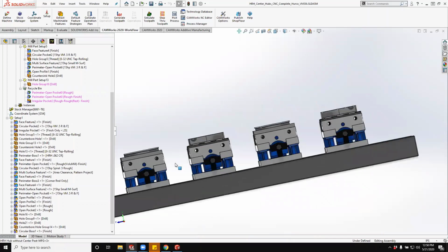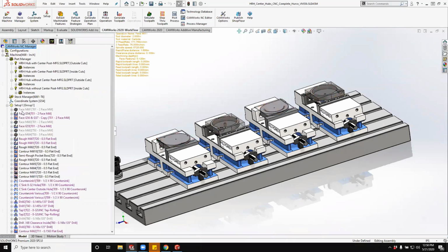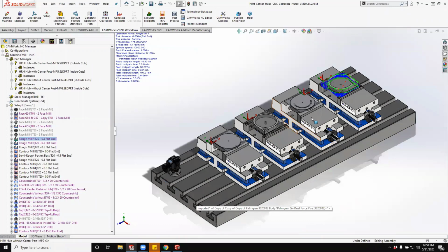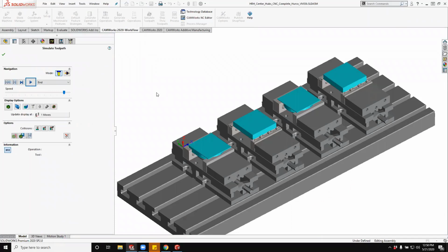And so when you go up to the CAM Professional, it gives you the ability to machine in the assembly environment. It's going to also add the volume mill. And so if we look at it, we've got some face features through here. And then if we look over here, here's that volume mill roughing. And we'll run it through our simulation so you get a little better idea of what that looks like. So we've added our vices as fixtures, our tables in there as a fixture. We'll keep it kind of slow. And let's run to the next tool.